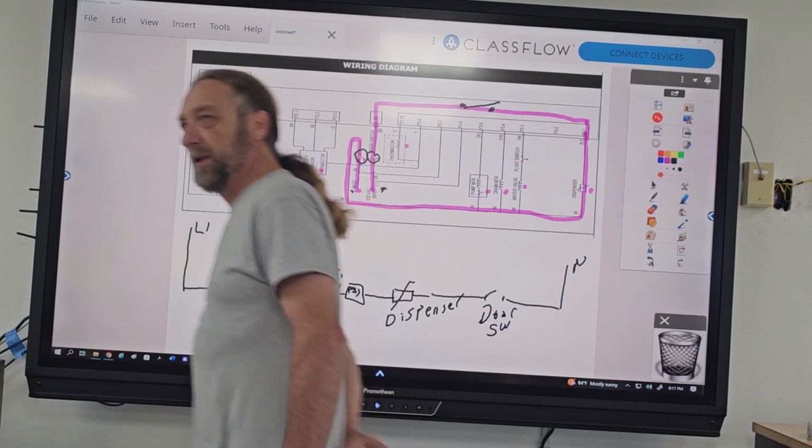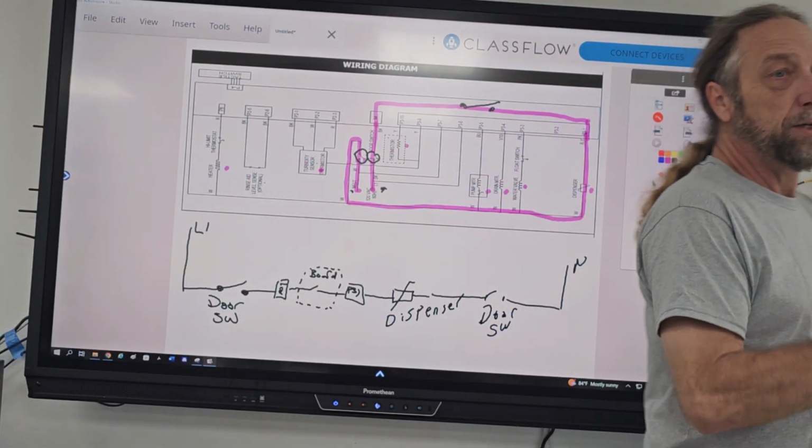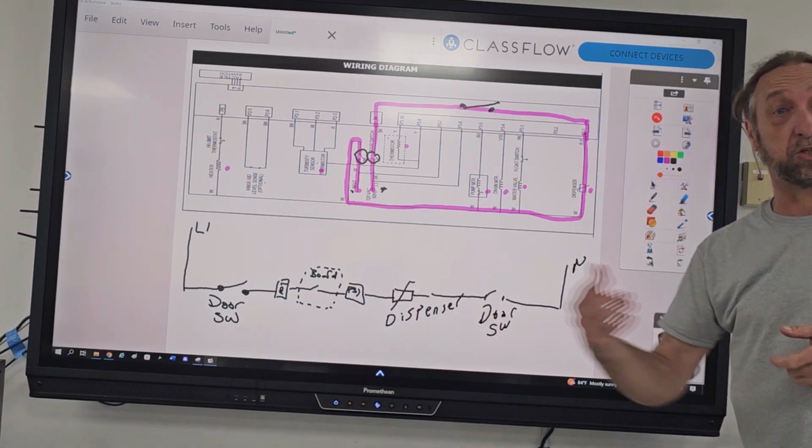So, what's important about that? Why is that important? Just that strip circuit that I drew. Okay. So everything is on one circuit, so you can test each component right there on that same circuit. You are right, but I don't think everybody understood you. So we did the circuit for the dispenser. What does the dispenser do? Dispenses the soap, right? It lets the soap in the dishwasher.